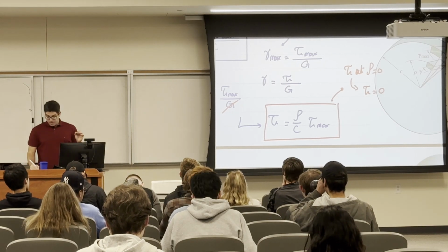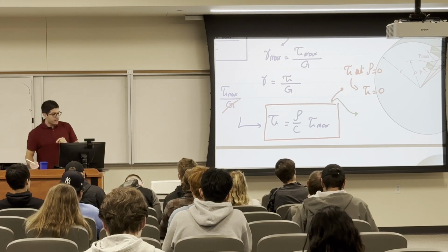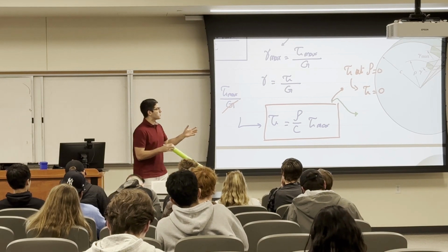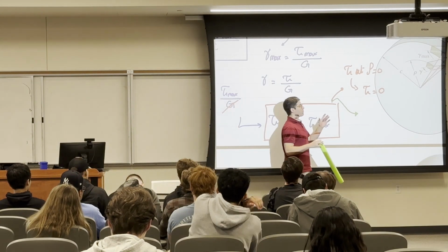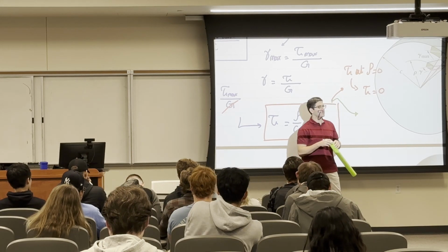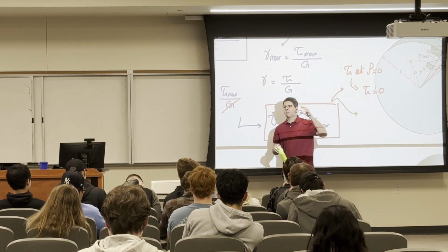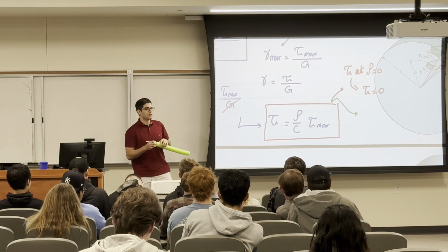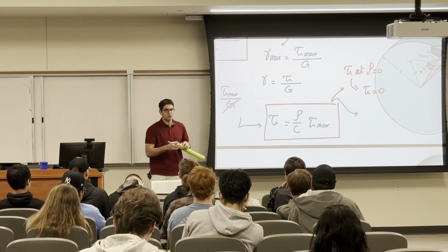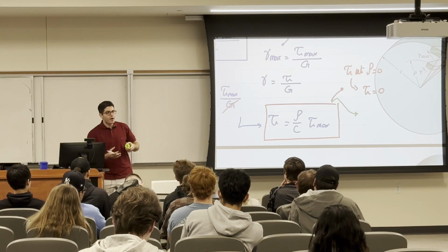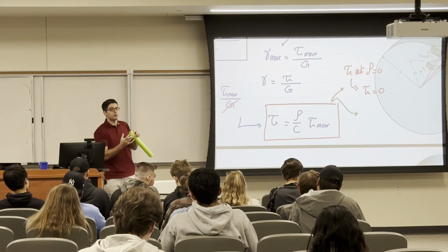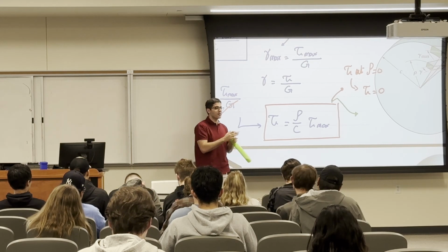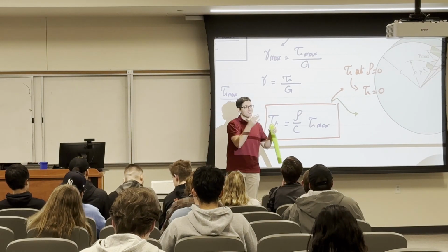And this concept is going to be of use when we take a lecture called composite section, when we have two materials, a strong and a weak one. So from this concept, if I have two materials, steel and timber for example, and you want to optimize the use of the cross section, where will you put the steel and where will you put the timber? Steel on the outside, and the timber in the middle. Do you all agree with what they said? The reason why is we have maximum stresses outside, so I want to put a strong material. In the middle, I barely have stresses, so I can literally put garbage in the middle, just to fill it.